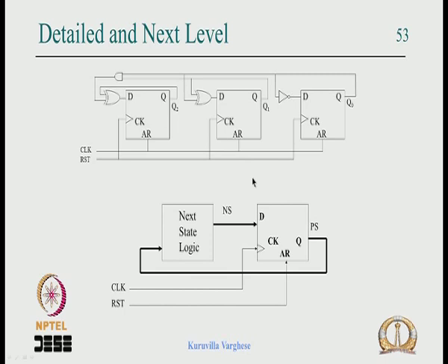So we have looked basically at the structure of a synchronous counter. What is the structure? It consists of flip flops and a combination circuit, and the flip flop output is called present state and the combination circuit is called next state logic. It's basically designing the next state logic. All the intelligence is in the combination circuit. The flip flops are used to control it, hold the value at every clock. This is like a gate which, when open, lets the next count come in at the precise interval, it's precisely controlled, every clock edge the count changes.